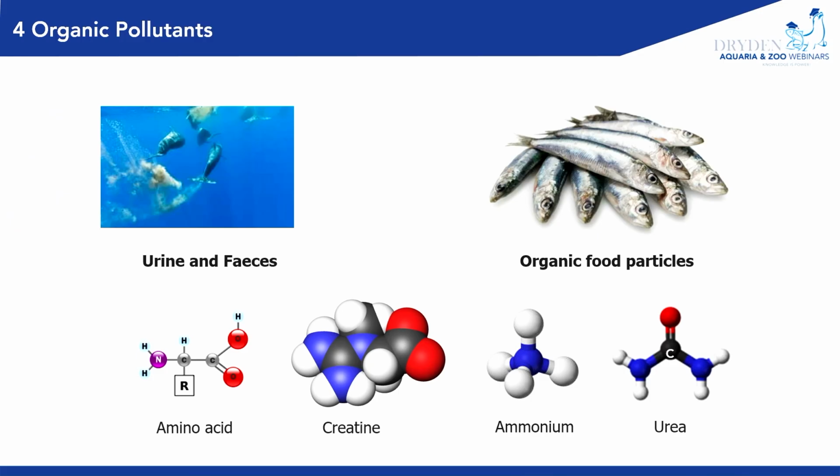So urine and feces, they're obviously what's going into your system. Chemically, they can be considered as all the chemical components you see at the bottom of the page. And those will, if you don't crop them out regularly and flush them to waste, accumulate in your system. And ORP is a measure of the balance between oxidizing and reducing agents. All the items that you see on this slide are reducing agents. And they will depress your ORP.